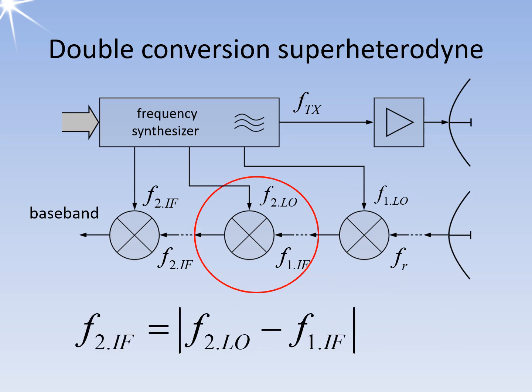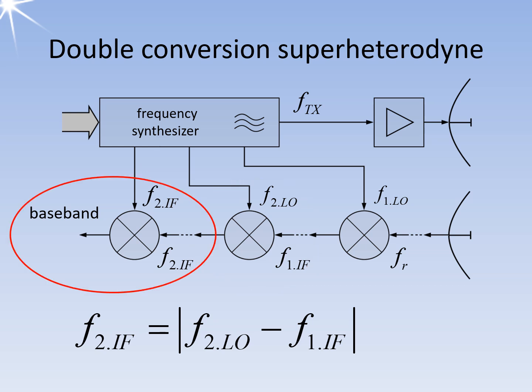The same principle applies to the second intermediate frequency, but now the input frequency is the relatively constant first intermediate frequency, without a large tuning range. An image frequency cannot exist here. The second intermediate frequency is low enough to ensure an extremely high gain while maintaining the required receiver bandwidth. The third down conversion uses the center frequency of the intermediate frequency amplifier as the local oscillator frequency, a process known as demodulation. The output signal now contains only a video pulse along with its superimposed Doppler frequencies.